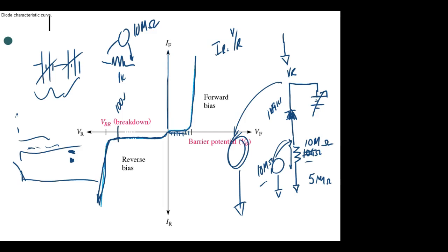So we've got a reverse bias. What's the current flow going to consist of? Minority carriers or majority carriers? Reverse bias. Minority carriers. What determines the amount of minority carriers? It's temperature, directly controlled by temperature. If we increase it, the atoms get more active, more minority carriers move up into the conduction band. The hotter it is, the more current, so what we should expect is, with it running, I come over and put a soldering iron across this, and we should see the voltage drop across this resistor go up.